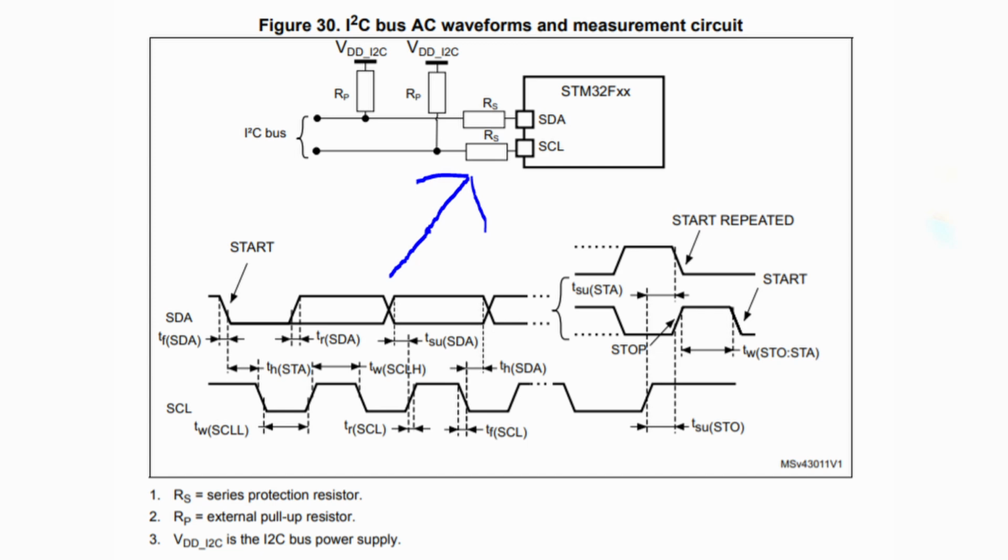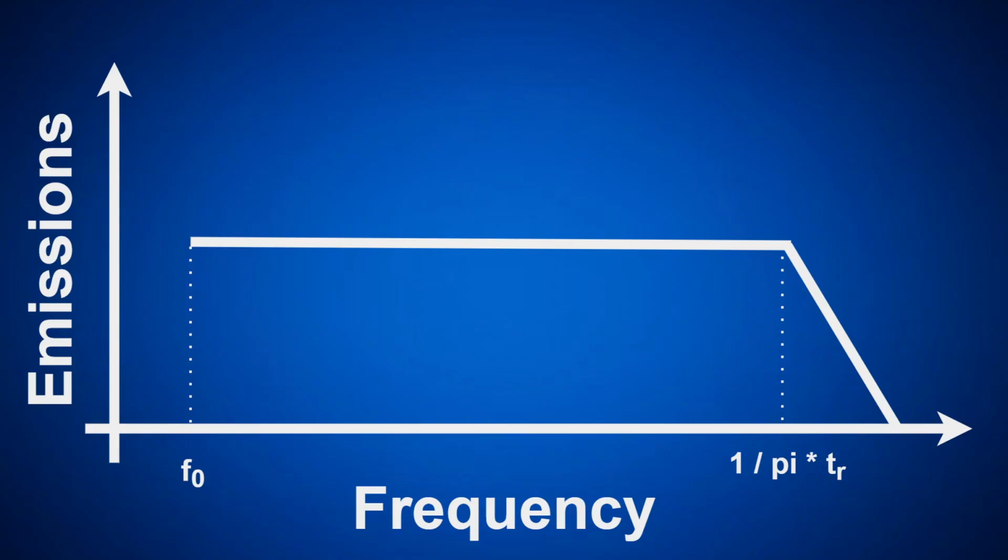At the circuit design level, there are a few different techniques that we can employ to reduce our common mode emissions. The first one is one that we previously mentioned, and that is to reduce the rise time of our periodic signals. As we saw with the differential mode EMI, adjusting the rise time of the signal has a significant impact on the harmonic content of the periodic signal. If you remember the graph that we looked at earlier, where the emissions started to level off past that breakpoint that was marked by the rise time of the periodic signal,